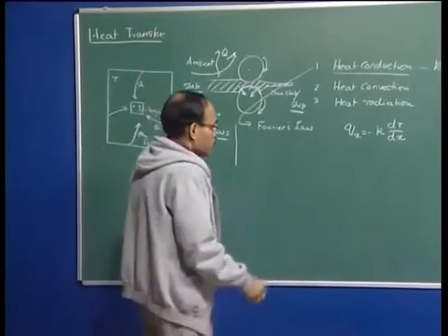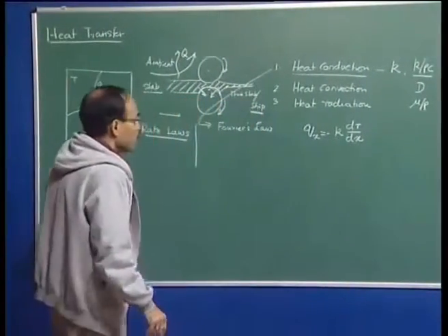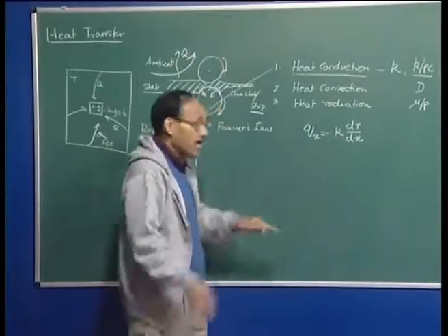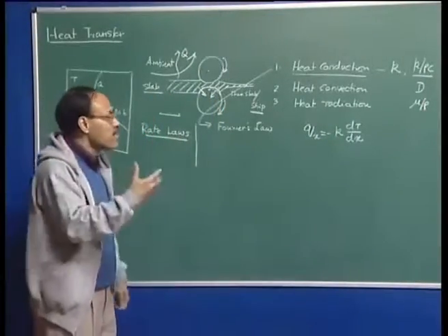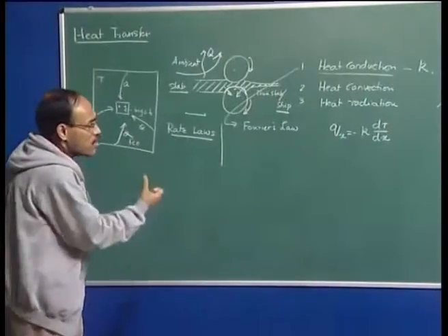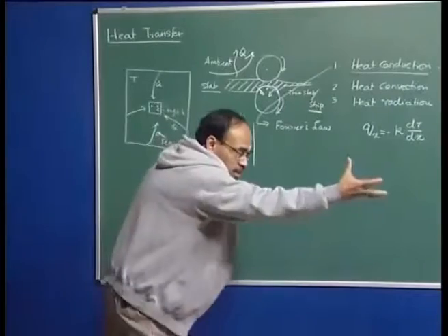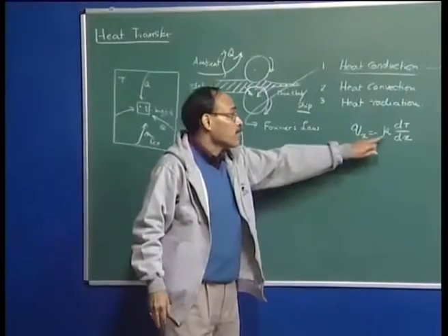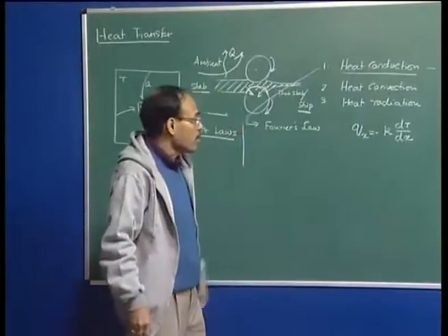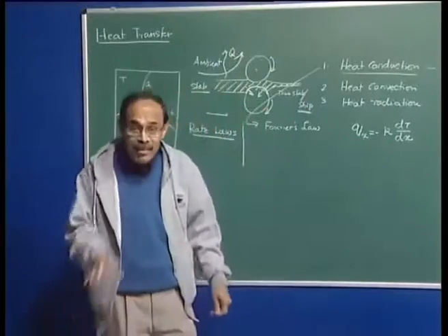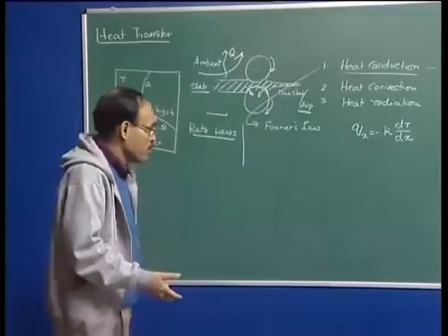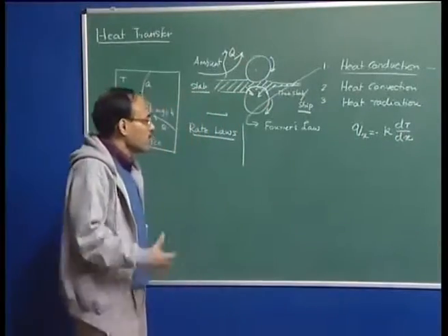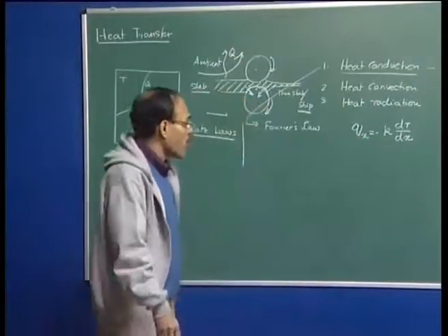Now, for this thermal conductivity, for a material, for example, I can have a qy, I can have a qz, and in that case I may not have the same k in all three directions. k may be a direction sensitive property also, or structure sensitive property, and in that case, if the structure of the material in this direction and in this direction are not identical, we can anticipate that thermal conductivity in different directions can be different. If thermal conductivity is the same in all directions, then we say that the material, or the thermal conductivity, is isotropic. On the other hand, if thermal conductivity is different in different directions, in the x direction we have kx, in the y direction we have ky, and in the z direction we have kz, then we say it is a non-isotropic material.